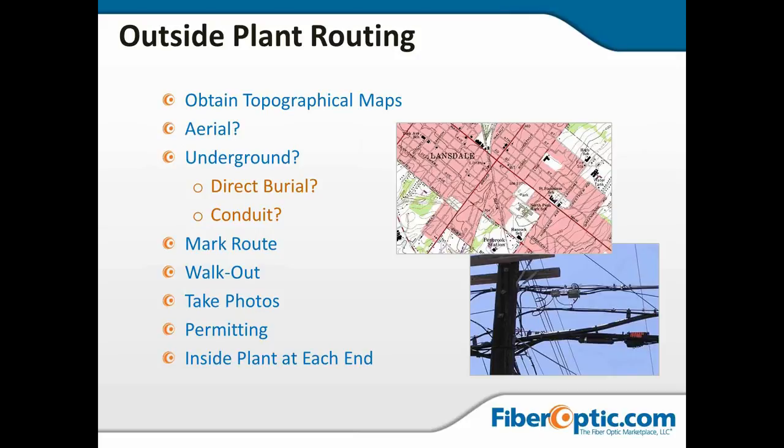And again, permitting. I've already mentioned permitting in the underground, rights of way, permitting on the pole, any kind of make-ready. We might get somewhere and find out that we're going to have to move everybody up, or if we're the low man in communication space, and the guys at the bottom right now are barely making clearance on a highway, then new poles are going to be set. We want to record all of that.